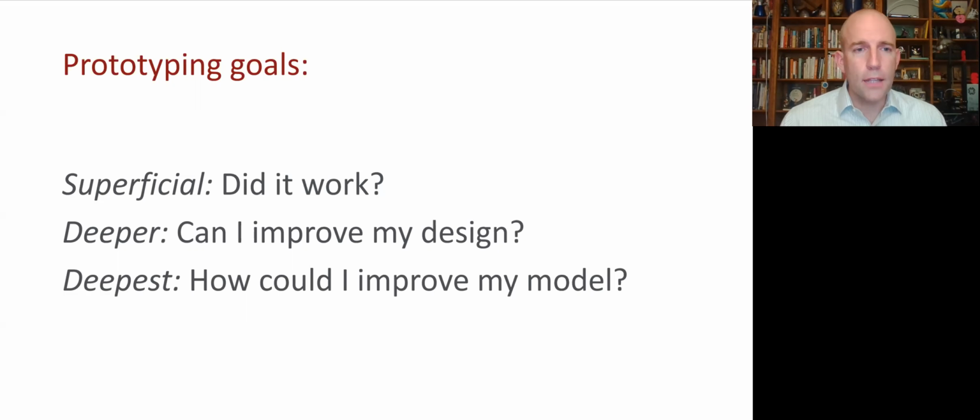For example, let's say we load our component and look at the way it deforms. And then we compare that to the way it deforms in finite element analysis or the implied deformation from our free body diagrams. If we see some differences, that can help us to make better assumptions about what the reaction forces will be, or use better simple models of stress for inverse analysis and back of the envelope analysis. And it may allow us to set up the computational problem better with more accurate constraints or more realistic loads. Those are all good ways that mapping these results back to our models can help us improve our design.